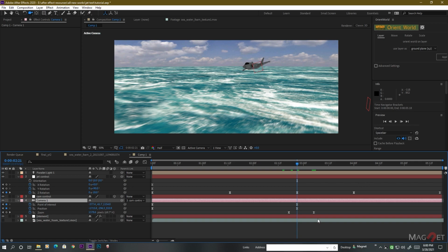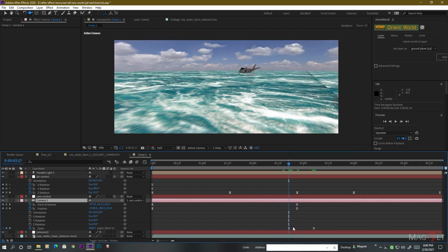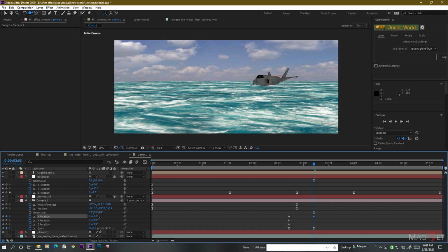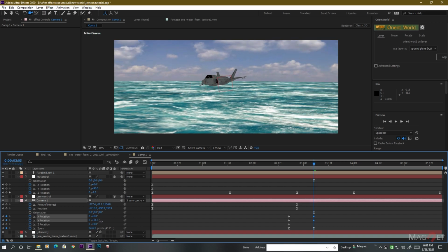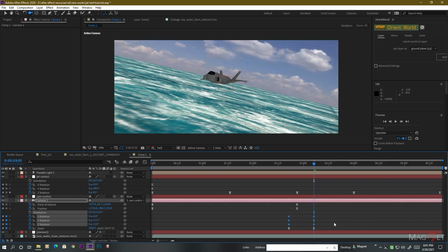and also we press Q and then press Shift and R, and then go to the initial keyframe of the camera zoom option and press A, and make some keyframes for the rotation values like X, Y and Z, and then come here and just rotate it like this, and also make those keyframes easy ease,